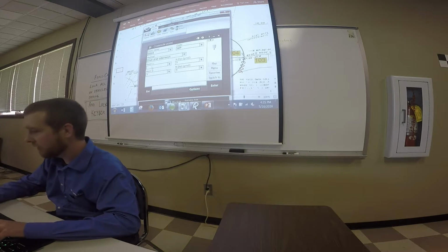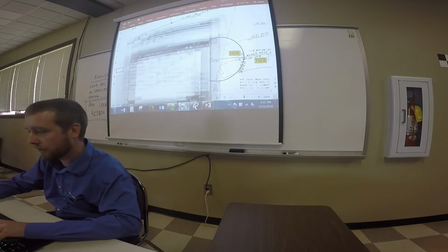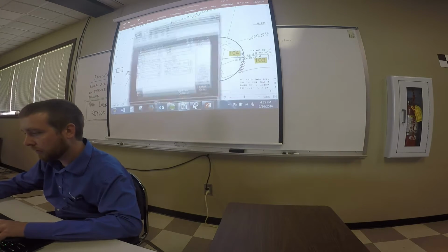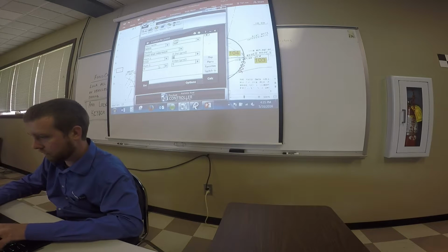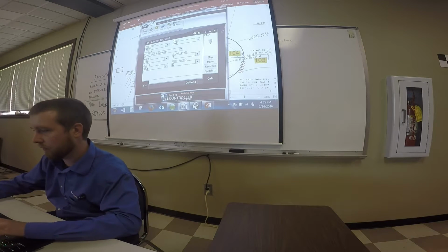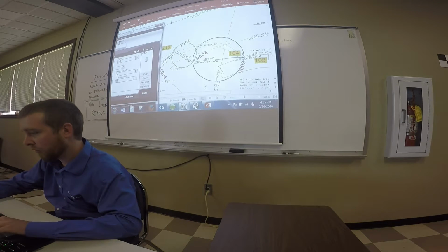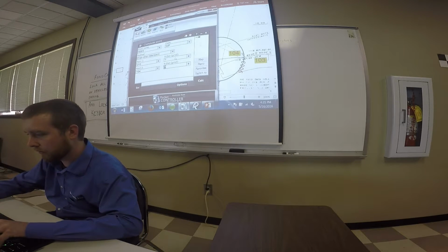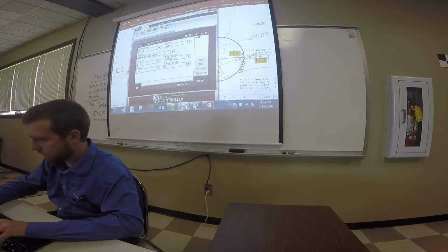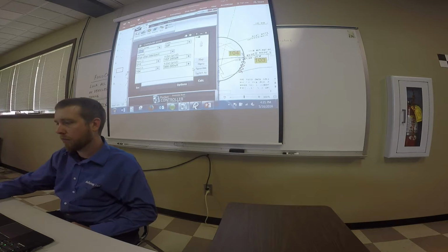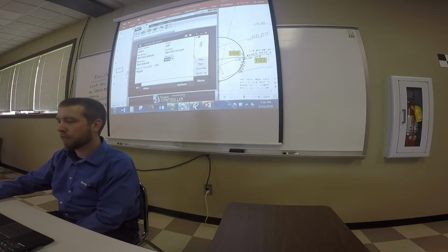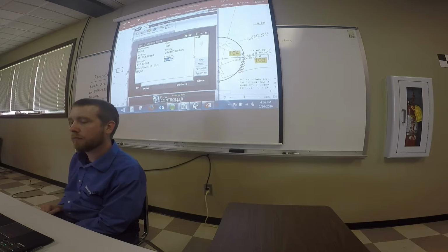The distance intersection is really helpful on older plats where they don't have bearings. I've been able to find pins using that where there weren't any pins along the road. I paced up the distance from the intersection that it gave, and then used the distance intersection and got within 10 feet of a pin.